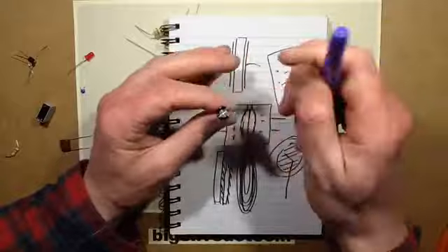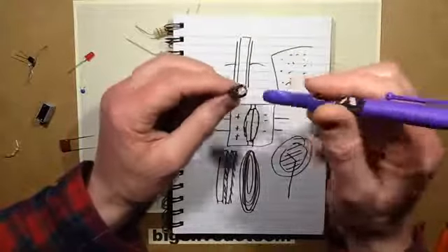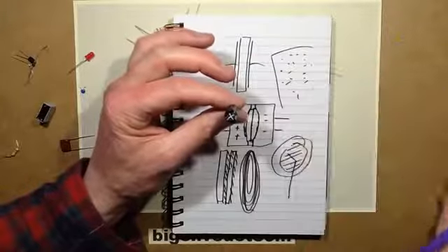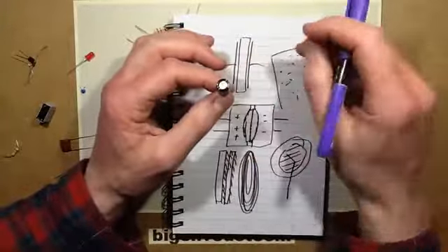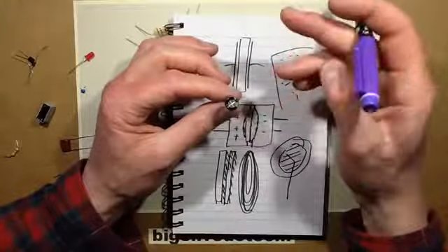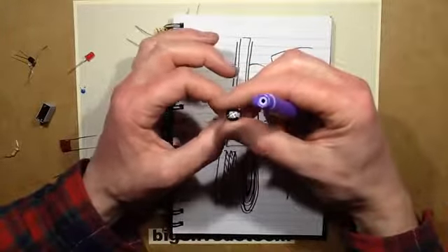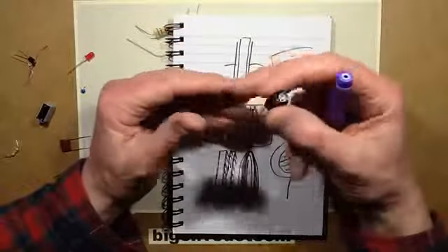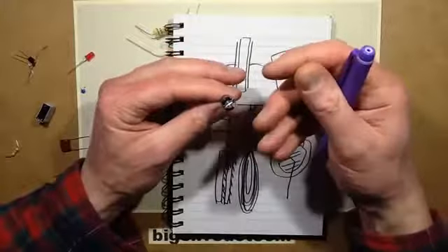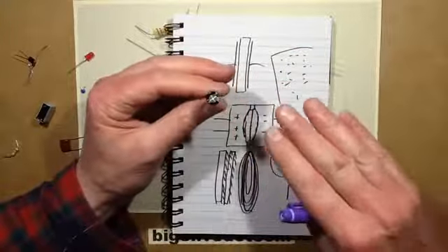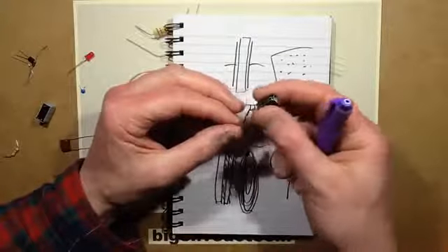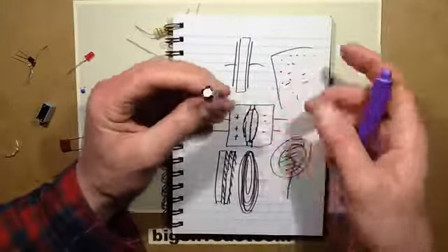And that's one of the downsides of, well, it's many of the downsides of the electrolytic capacitor. Traditionally, all the old video games from the 80s tend to suffer problems after a while with what's called drying out of the electrolytics. They still measure the correct capacitance, but their equivalent resistance, the resistance to current flow through them, changes, it increases. And what that means is that they stop doing their job properly.